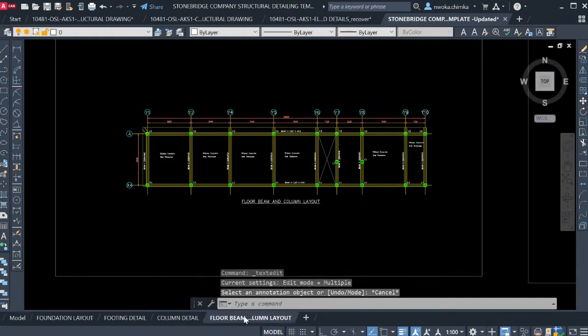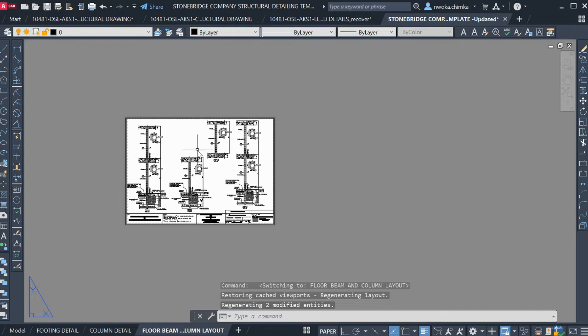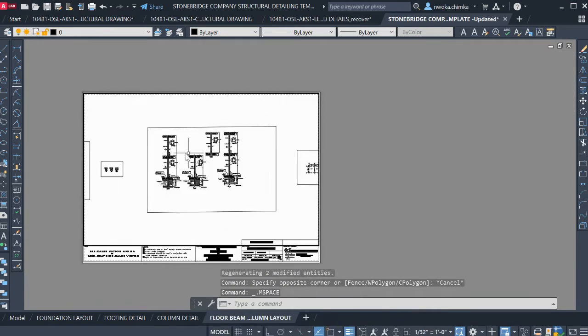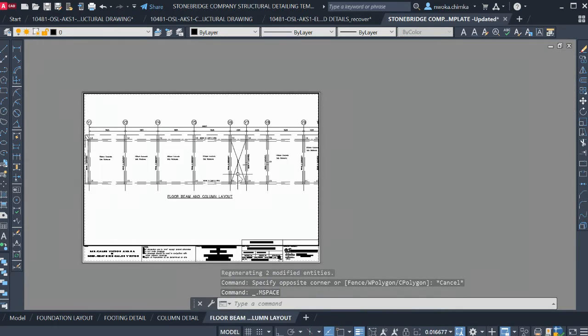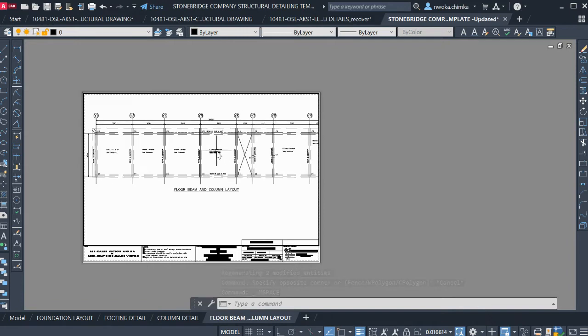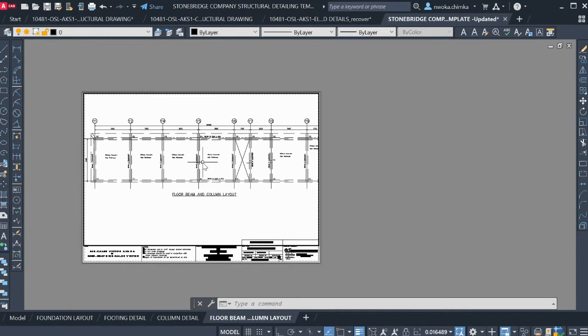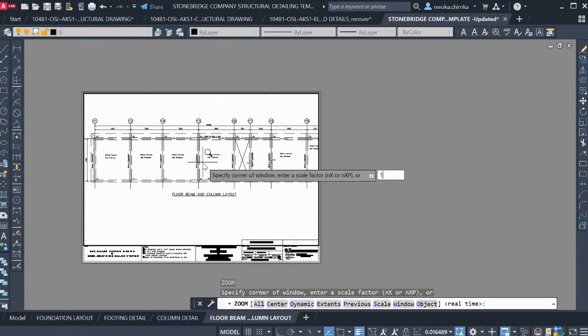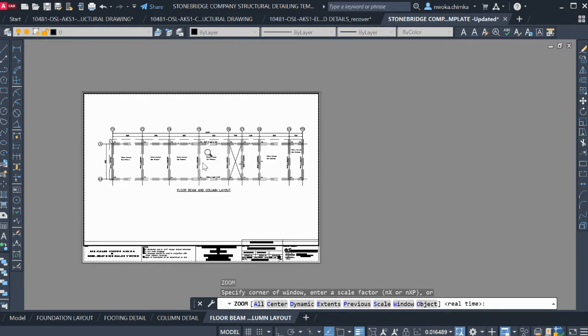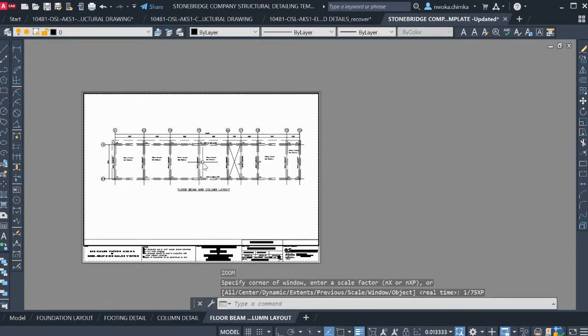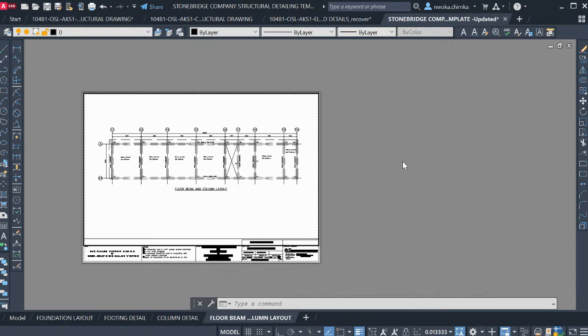So we'll now go here right now, click at this place right now to bring in that particular one, which you can see there. So click this place right now. Let us use a scale of 1 is to 75. If it works, hit enter, 1 is to 75 SP, and then enter. That works perfectly for us. You can see there. So we can just use pan to pan it up and keep it somewhere here.